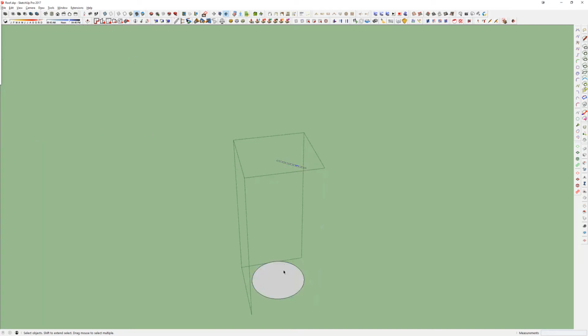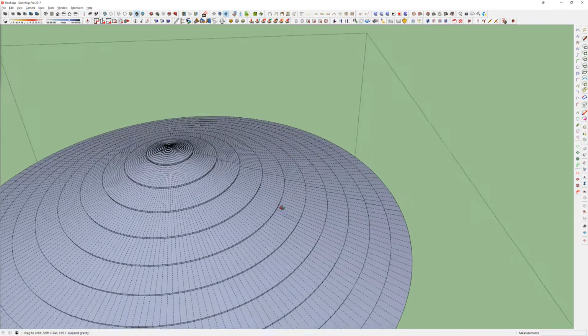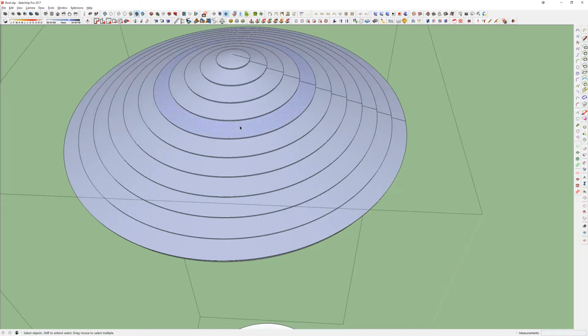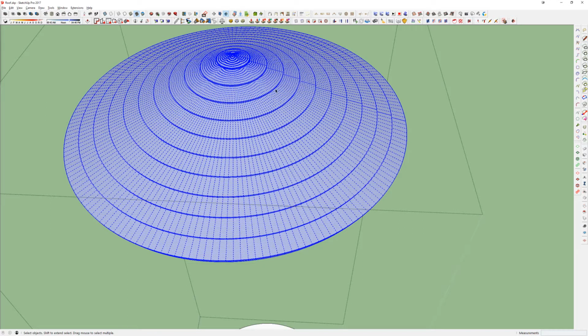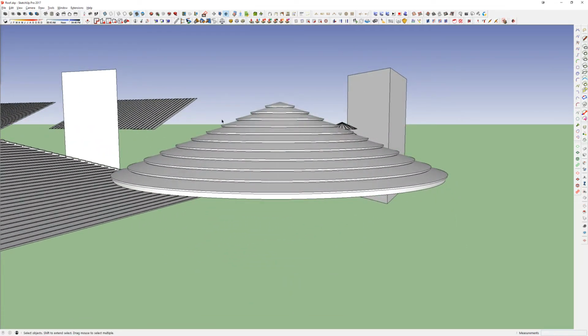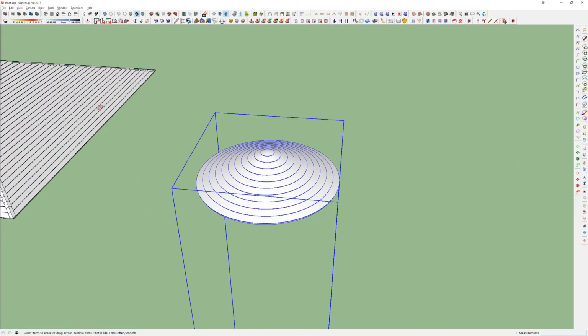And just like any other trim, I'm going to select this and then hit F for my Follow Me command. In just a second, if you remember, my turret I have built as a pretty high segment count, so it had to go through all the segments. But that's it. It's just simply using the Follow Me command. And here I'm just going to use my clean command, which we've used many times now. And you see it gets rid of that line, and hit Shift R to reverse faces. And there it is on the round. So it's pretty quick and simple. In fact, it's even easier than the rest of these.